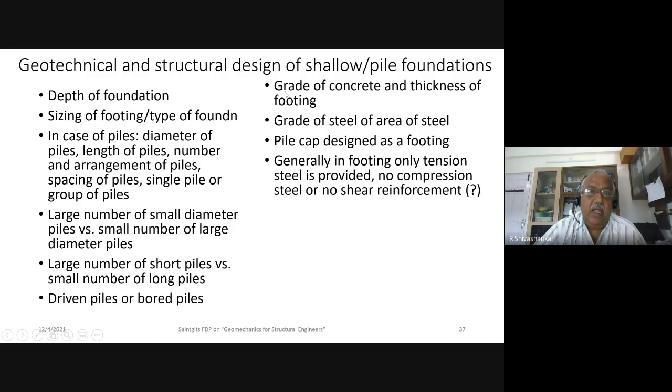That means I'm transferring the load from the superstructure to the pile by skin friction and end bearing. And in this process, there will be some settlements. The skin friction will be mobilized only when there is settlement. I don't want the settlements to exceed the permissible limits, either in the case of single piles or group of piles. So that comprises the geotechnical design.